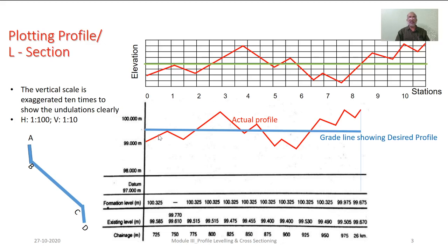So obviously there is a vertical ordinate as we consider the placement of this particular blue line and as we consider this particular red line, the vertical ordinate tells us the amount of fill required. So here the way you see, this is the placement of the station, say at 99 meters. But for example, I wish to have this particular point set at some 100 meters. That means I have to raise this ground by filling the existing ground level by 1 meter.